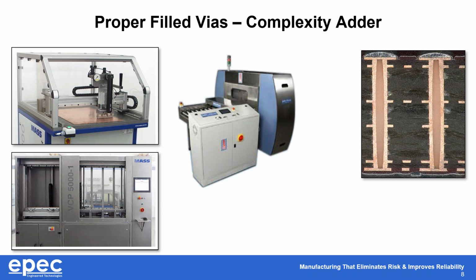So you have to make sure that it sits, many times an hour, if not two, in an oven, so that you get the consistent temperature throughout the entire laminate. Right, you can't just throw it in at 700 degrees, leave it for 10 minutes, and think that the whole laminate is going to be the same temperature all the way through. So now you've got to do that just before you do it. Now it's got to come right out. It's got to go right into fill, right? And then it's got to go into cure, and that's the same thing, right? That's got to sit for at least an hour, if not more, right?